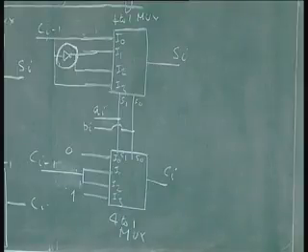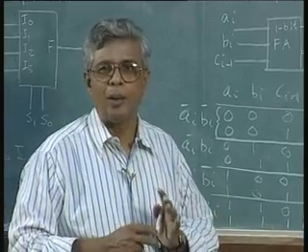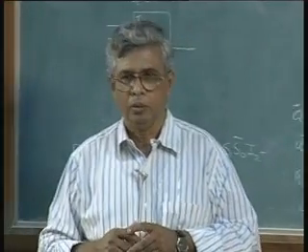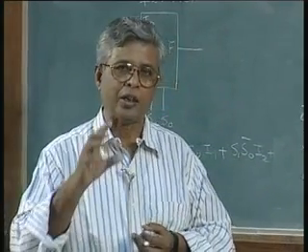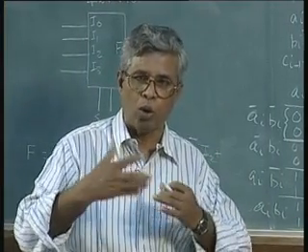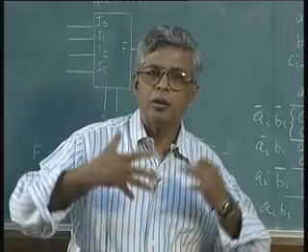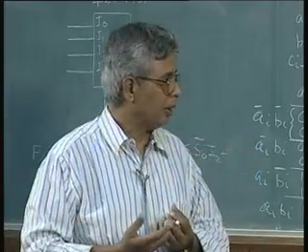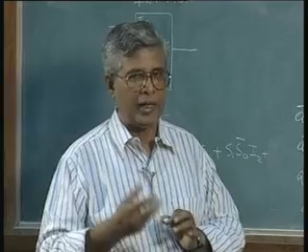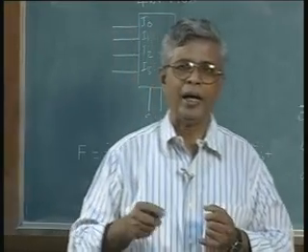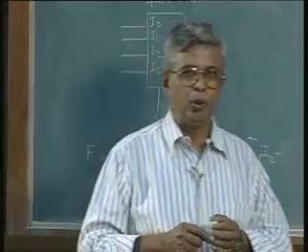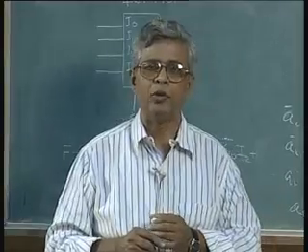This tells you how to proceed with available components. As an example, I took the multiplexer, I took the full adder, so that the concept is clearly understood and it is also simple. Think of this as a bigger and bigger problem. As the problem grows, we can get more and more complex circuits using multiplexers. It can be proved, just as we proved in our earlier combinational logic course with gates, that all logic functions can be implemented using AND OR inverters to start with, and further simplified to NAND gates and OR gates. It can be proved that all combinational logic can be derived using multiplexers.